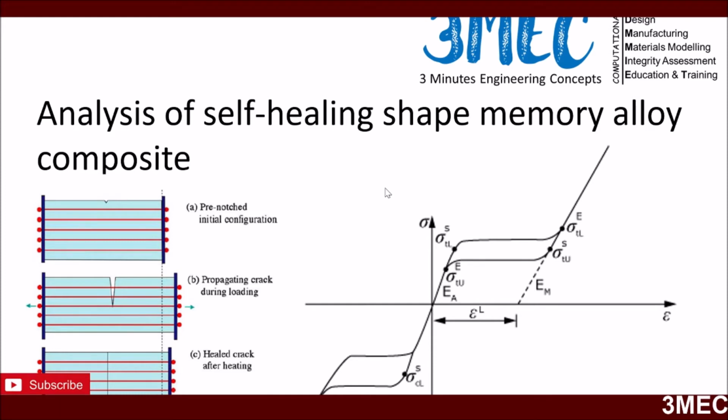We worked on this a long time ago, I would say almost 10 years ago, so my knowledge might not be that updated at this point from the research perspective, but what we did in that case was we expanded the shape memory effect, which is the pseudoelastic effect, to the elastic plastic part as well, because after a certain amount of deformation, once all the transformation has occurred, you will have plastic deformation in this material followed by failure due to void nucleation and growth. So that's what we did in our paper, and I will give you the reference at the end once I finish everything. So this is the problem here.